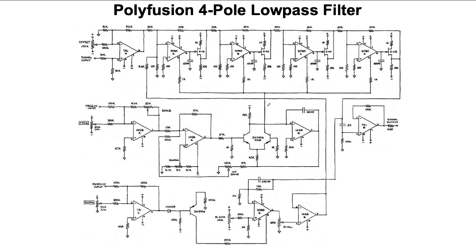So this basically works the same way as we saw previously in the lectures about oscillators, but here instead of a positive voltage, we have a negative voltage to create a reference current flowing through the resistor this direction. The rest of the setup is pretty much the same. We have this op-amp here that's designed to keep this collector node at a fixed potential. Here that potential is ground. The 15K resistor here is dealing with non-ideal op-amp effects. And the 100 picofarad cap here and this sort of local feedback loop is just for stability. The main logical feedback loop is happening all the way throughout here.